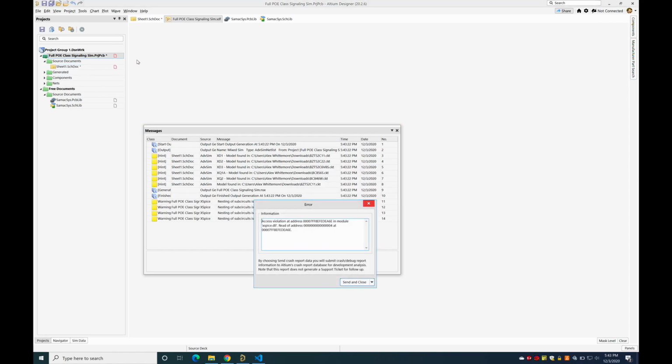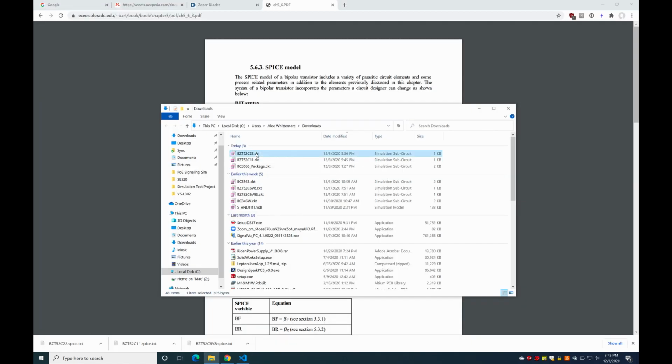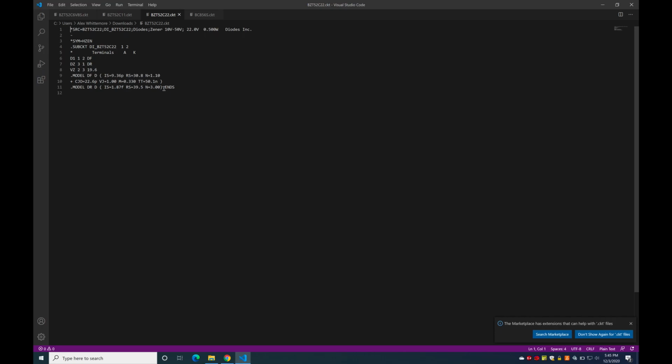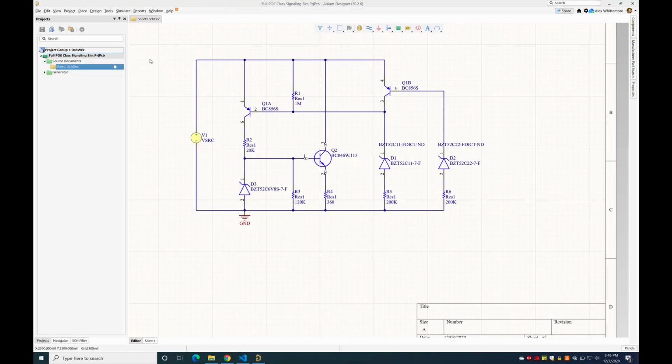Now what we're seeing here is that bug I was talking about earlier, where the Diodes Inc. models had the .ends statement not on its own independent line. If I go back and fix that, this suddenly starts working correctly and doesn't error out.